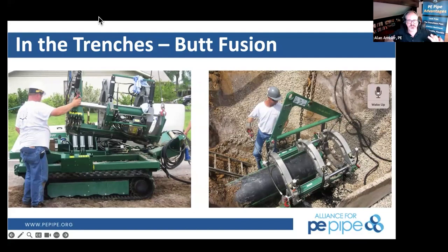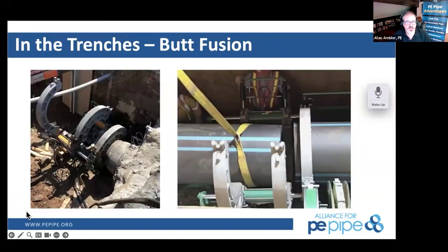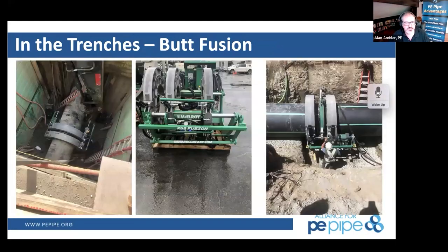Once that 57 stone settles around in the haunch of the bottom of the pipe, most of the protection is going to be provided by compaction of that backfill that's on top of it in that manner. So hopefully that helped answer the question. For larger pipe, obviously you're going to have more effort, larger, wider trenches to be able to get access to the haunch and make sure that we compact that.